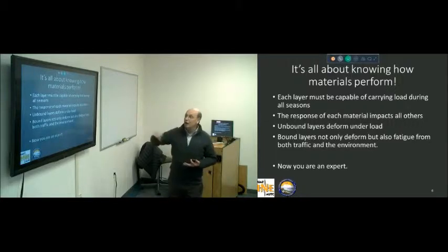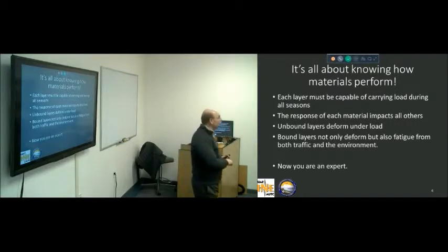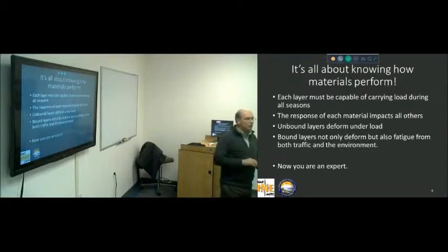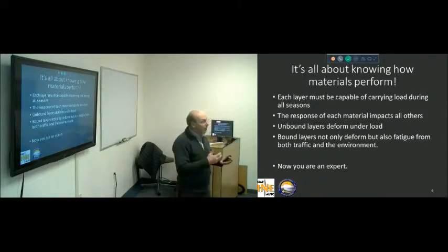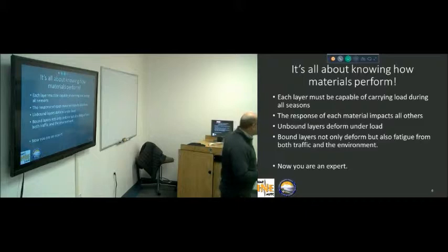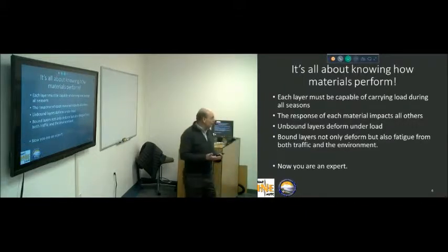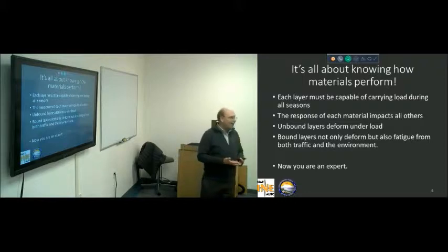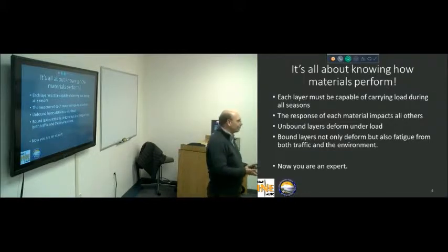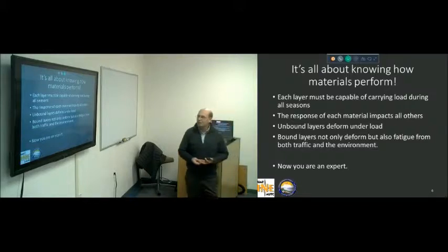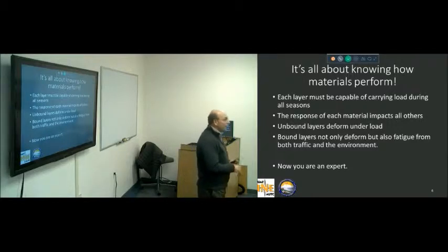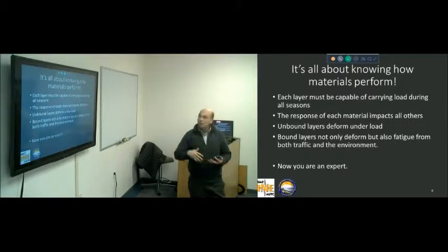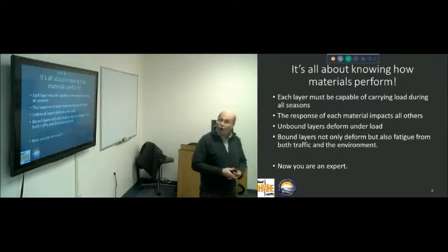We also have to know that unbound layers are going to deform because of load. We'll go into that in a little bit more detail. And the bound layers not only deform under the load, but they also crack, either due to the load itself, fatigue cracking. Sometimes we call that alligator cracking, or chicken wire cracking. I prefer the term fatigue cracking because it's truly representative of what's going on there. We have thermal cracking as well, and deformation due to rutting, due to material properties that don't resist that, and abrasion, for example, under studded tires. All of those things go in that.